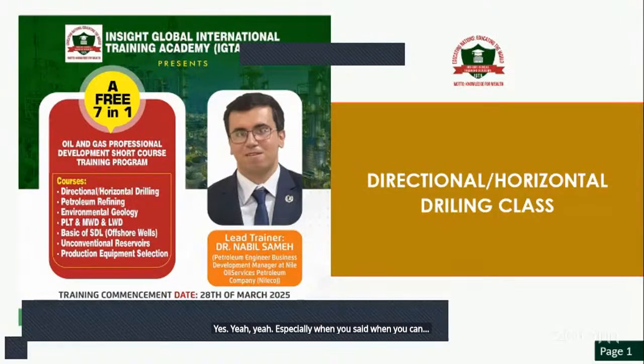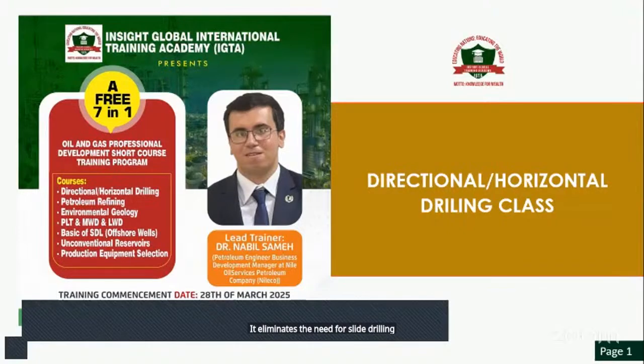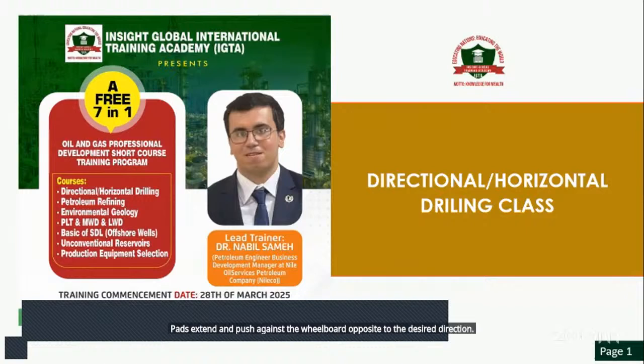Okay, actually for the RSS, as I said, which is an advanced directional drilling tool that allows continuous rotation of the drill string while steering the wellbore. It eliminates the need for slide drilling, and gives precise trajectory control in directional, horizontal, and extended reach wells. How it works: the tool detects the well trajectory by using measuring while drilling or logging while drilling sensors. Pads extend and push against the wellbore opposite to the desired direction. This redirects the bit without stopping rotation.